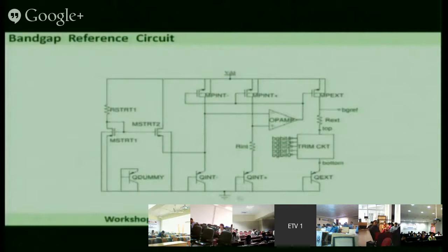Here this is the current source. Again there is a PNP transistor of a different size compared to this, and to generate that KT by q term, a resistance is used, and at this output the KT by q thermal generation will come, which has a positive slope. Here VBE is not used, because we are taking the voltage across this resistance. So the value of this resistance is adjusted so that the slope at this point becomes the same. Only thing is, here it is decreasing, here it is increasing, and we are adding these two, and then it is being fed to another stage.